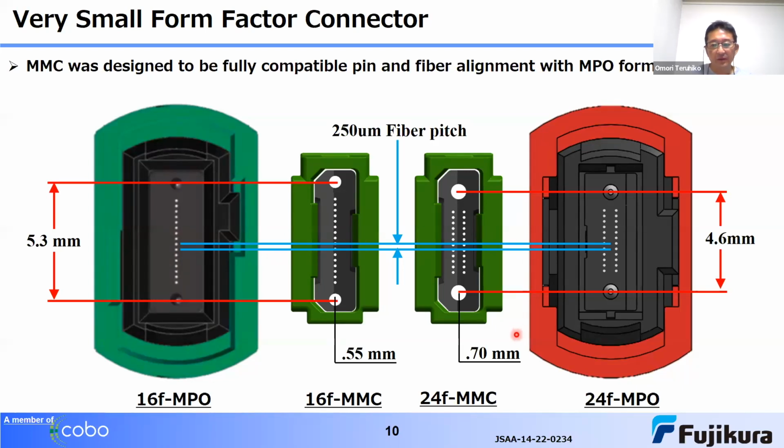And also for 24 fiber MMC and MPO connector has a 0.7 millimeter guide pin hole and with 4.6 millimeter pitch. So actually MMC connector is designed to be fully compatible with the MPO format.